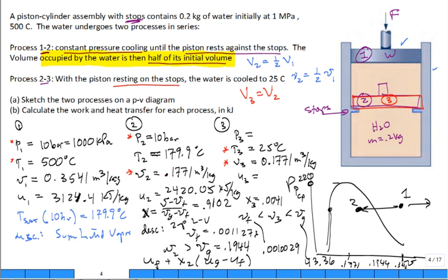To draw this accurately on a cartoon, I need to really kick this way out and put state 2. It's even going to be worse than that. It's hard to draw it to scale here because when it cools down, it stays at constant volume to state 3, doesn't it? But this edge goes so far out that it's now low quality steam at state 3.